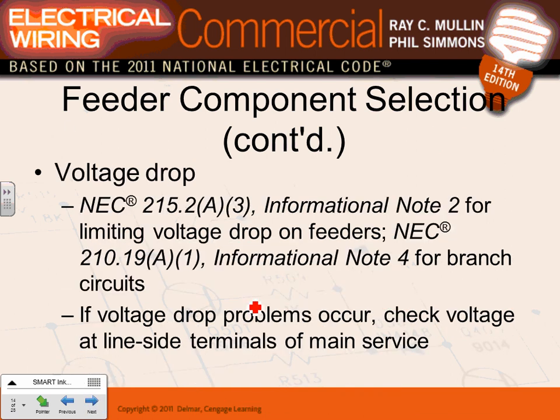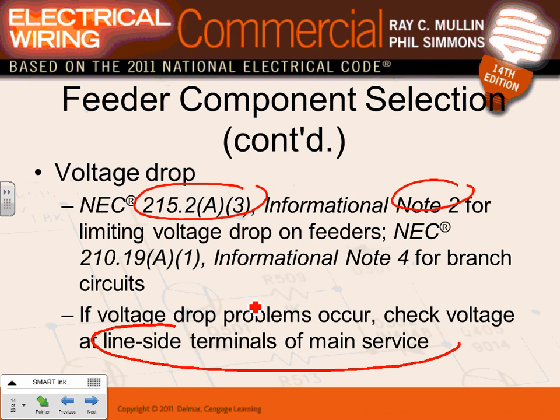Okay, voltage drop. We talked about voltage drop, guys. It's actually a footprint on the feeders. You have to size your feeders to be able to handle the voltage drop. If you want to know that you have a voltage drop problem, you have to check your voltage. But a lot of engineers, from the get-go, size based on the load and up the conductor one size. If you don't want to do that, you do a voltage drop calculation.